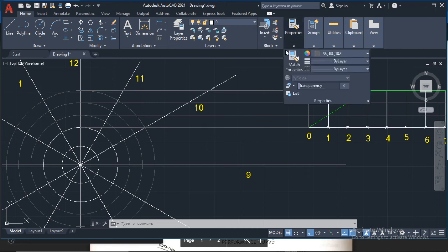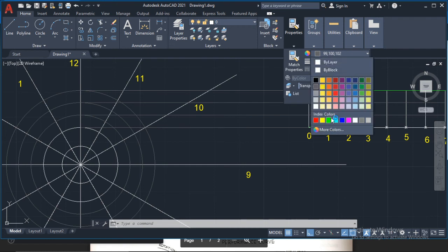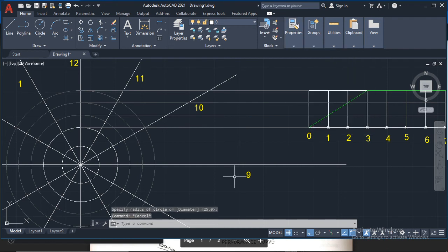And I'm going to plot it by using a spline. All right. So I'll just select spline, S-P-L-I-N-E. I'll start here, because that's the first point. I'm going to turn off ortho. Now, our second point. Where's our second point?